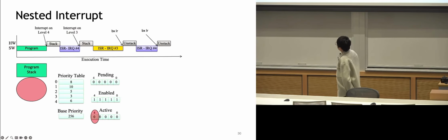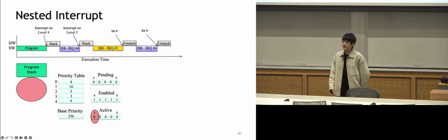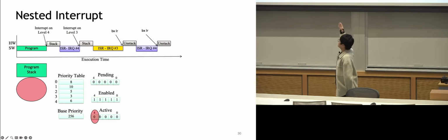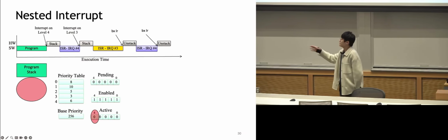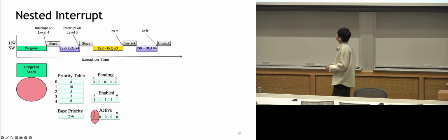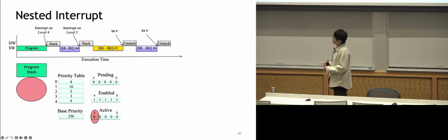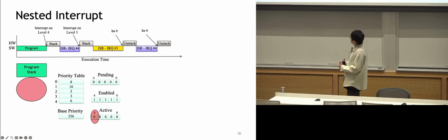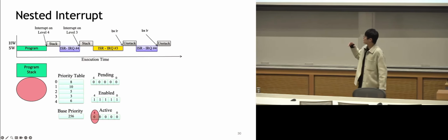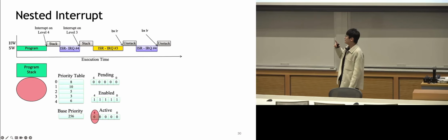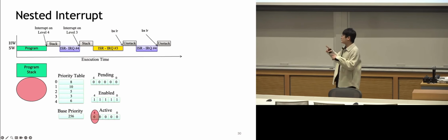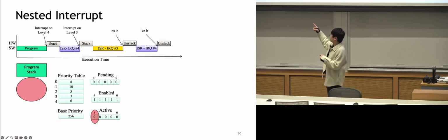It's after the stacking, yeah. So you will stack, and then it became active, and then it pulls down the pending bit on that same request. Yes. So what is the scenario when the pending bit and the active bit are 1 at the same time? There shouldn't be that. As soon as the active goes on that one, if there's only 1 interrupt request, that means that will pull down the pending.